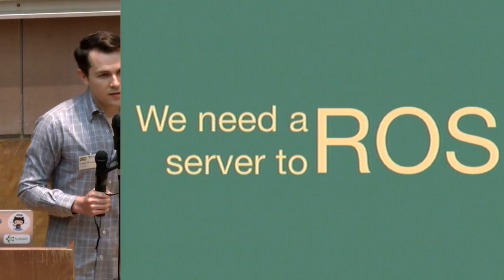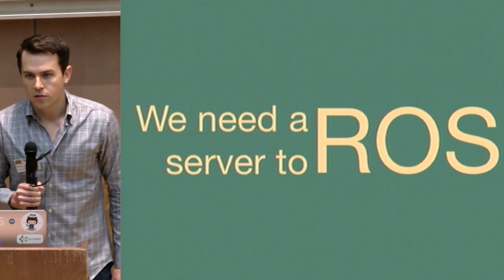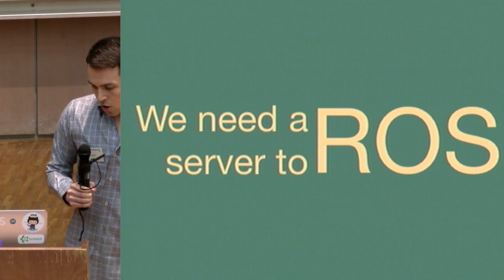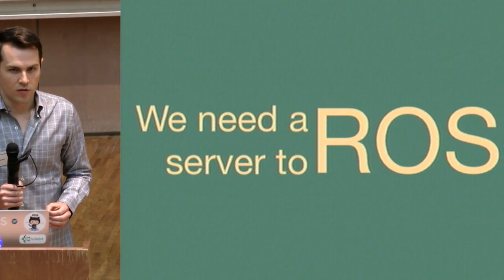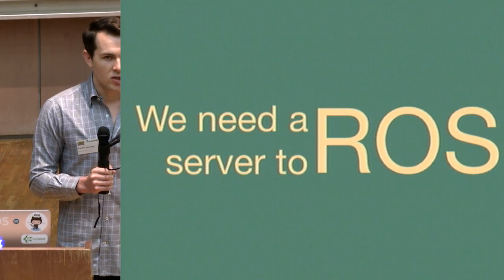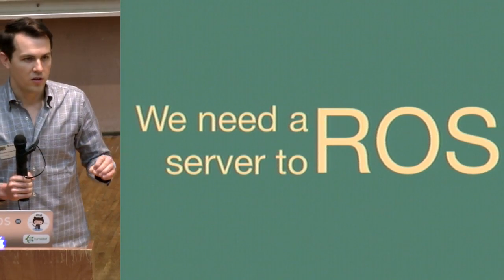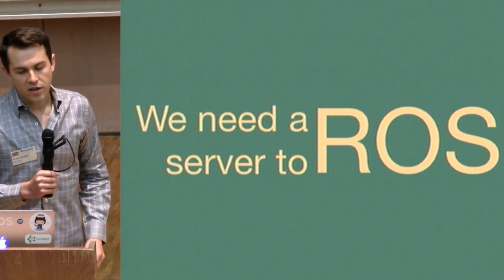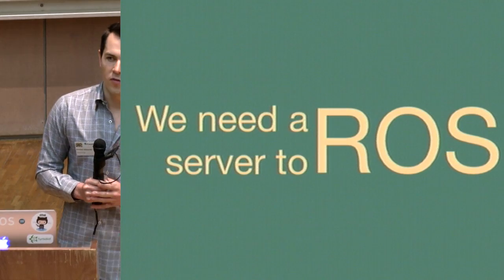But how do we get this computer and a web page running on this computer to talk to a robot somewhere else? And that's where RosBridge comes into play. RosBridge creates a WebSocket connection between your browser and your server. What that means is that WebSockets provide a bidirectional, low-latency communication between your browser and your server. So it opens up the connection, it takes in a JSON message, and then it converts that JSON message into a ROS call. And the same works in reverse.